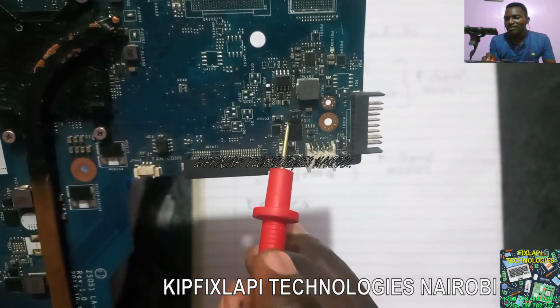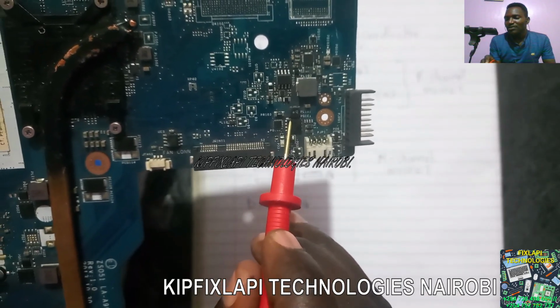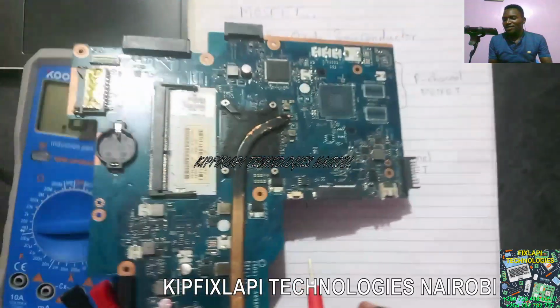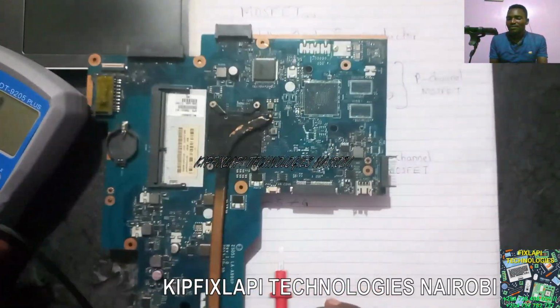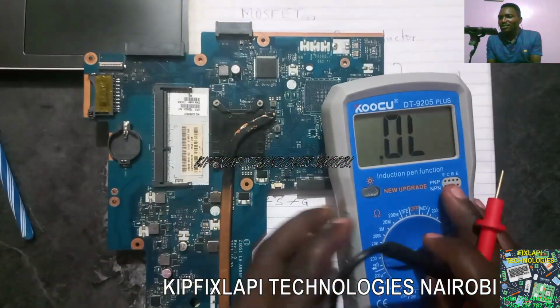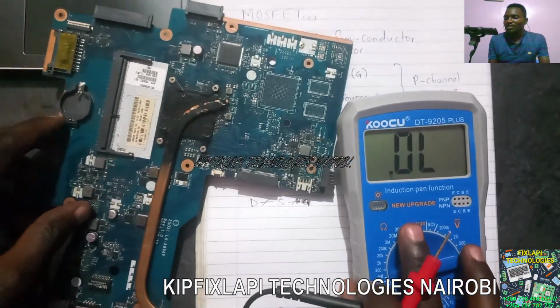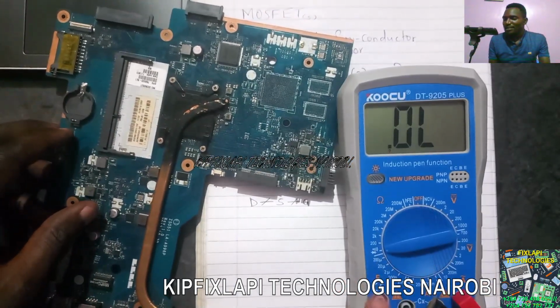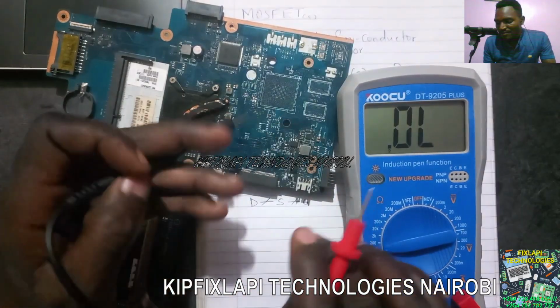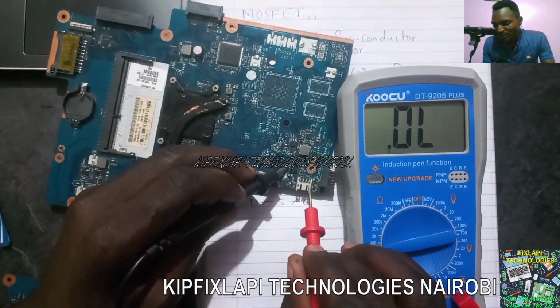So for me to test for faultiness of this MOSFET, first thing I need to make sure my meter is in continuity mode. Let me put it here, guys, so that you can see it together. So I need to make sure my meter is in continuity mode, and it is in continuity mode. Then my other probe, I should place it at one of these pins.